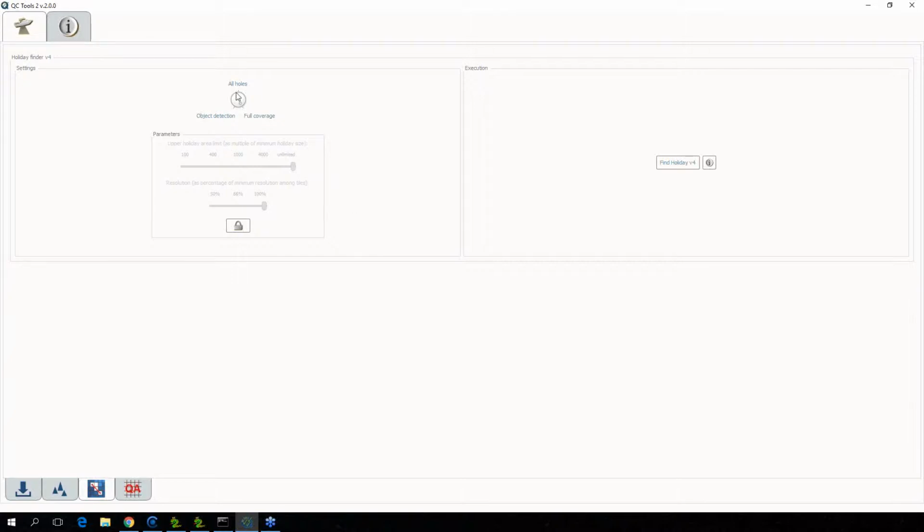grid nodes that are unpopulated. So I don't quite recommend that. I'm sure there's some use for it. But just be mindful of making sure that you have selected the correct toggle for the coverage requirements for your survey. If you forget which one you've done, the file name will actually reflect all of the parameters that you've chosen here, which is very useful. So it retains not just the coverage settings, but all of these other parameters here. These are user optional settings.